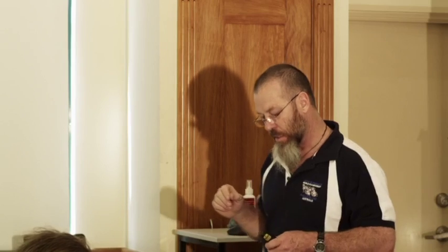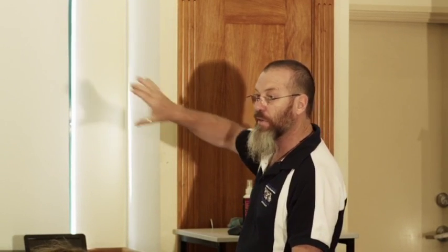You look at N1 tile there, even in the second row, it's just got that little blank in there. And where it's got that blank, that means you just go straight to table 9.4 and get a nominal connection for it. So all you need to do in N1 tile is tie your roof battens down to your roof frame, and everything else is a nominal connection. Okay, it's as simple as that. Where it's just got that little blank there, that means nominal connection.